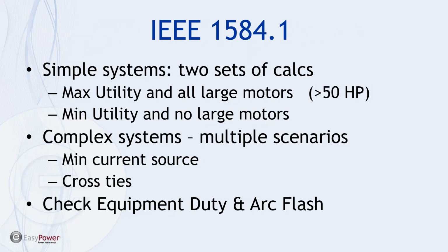IEEE 1584, when we're talking about arc flash calculations, suggests that you want to have an analysis with motor contributions, all large motor contributions, and without.